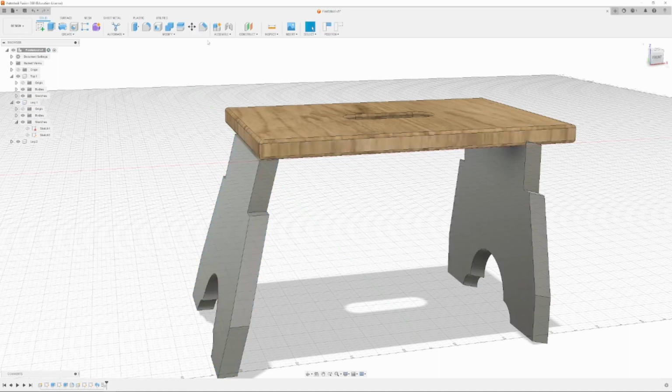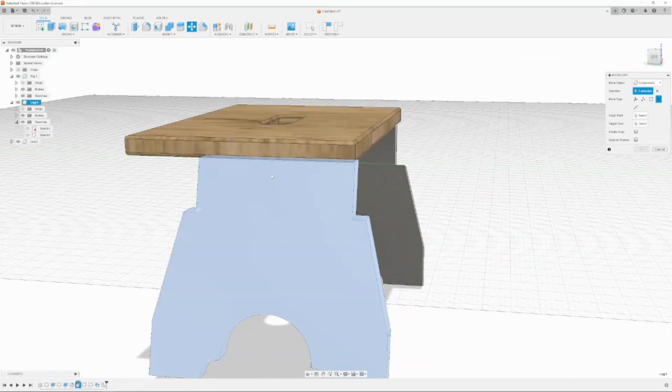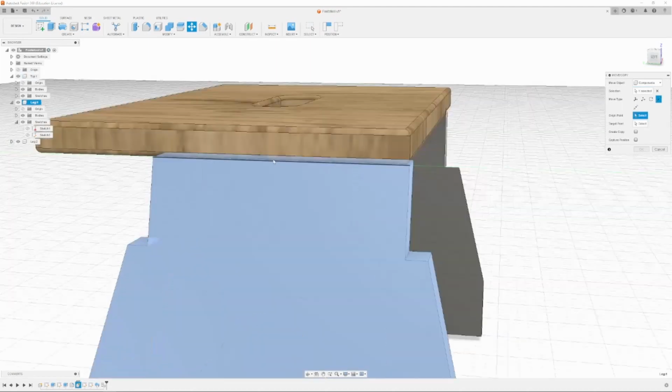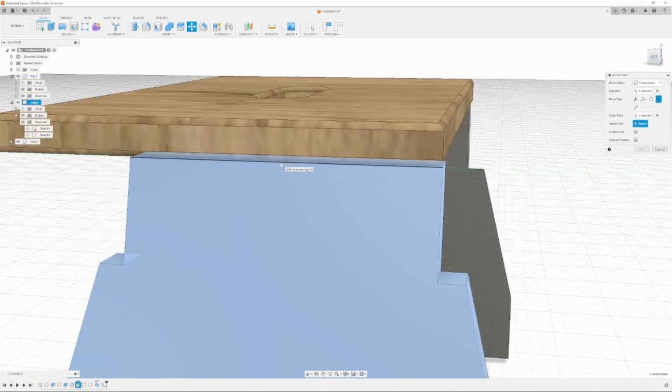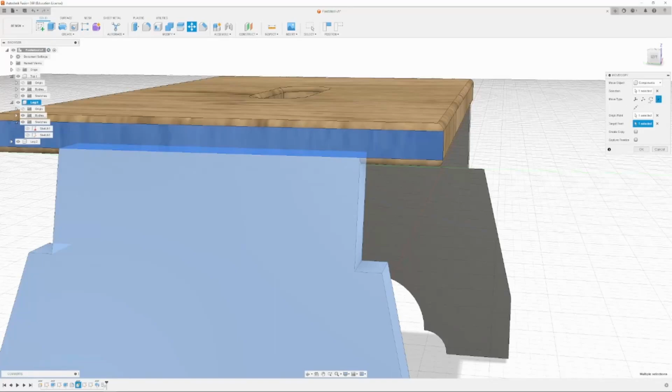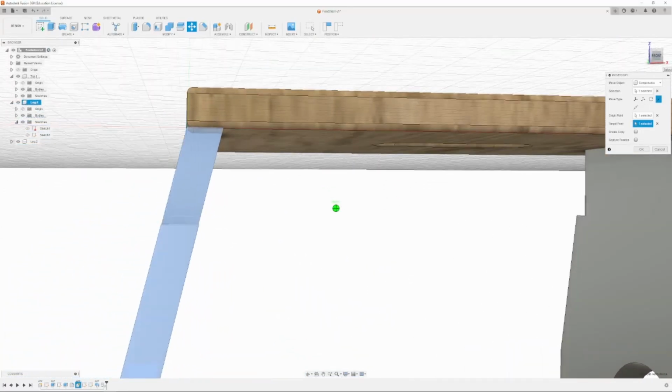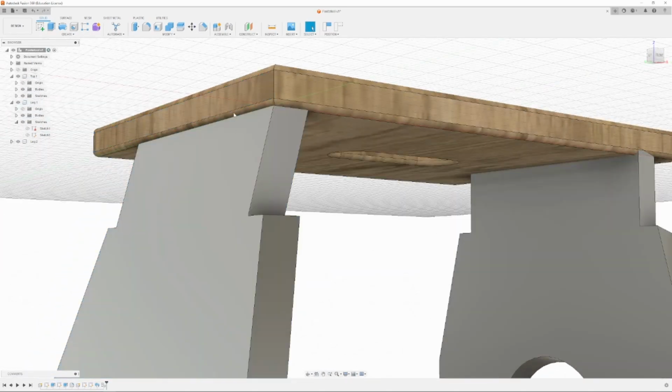And then I can go ahead and rotate this one too, but I'm going to move this one into place first. So I'm going to do point to point, and I'm going to select this component, and then the origin point is the midpoint of this one. And so when you hover near there, it should give you that point. Oh, and then the target point is this midpoint on this part. Okay, and because I did the fillet, it would have been easier if I did it later. Actually, I just did it in the wrong place.